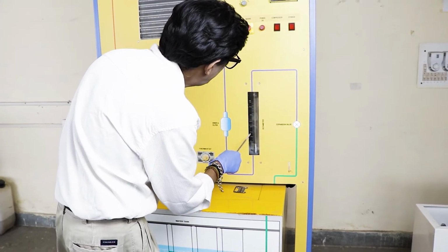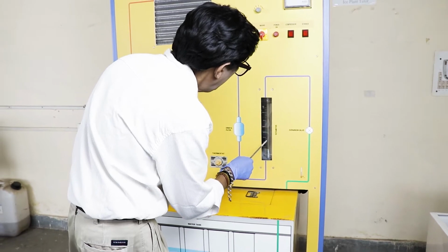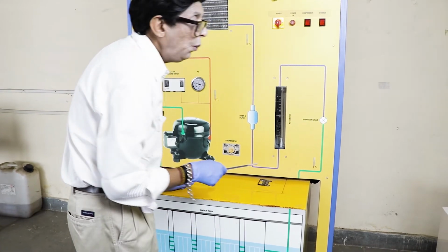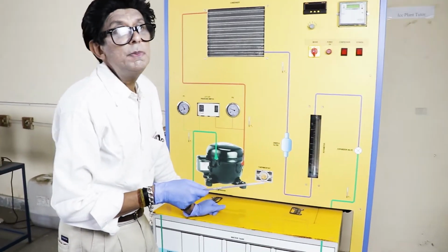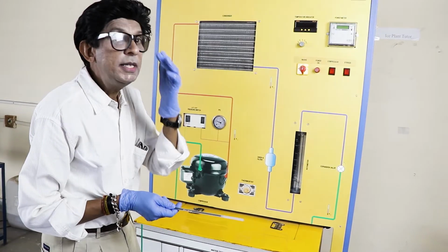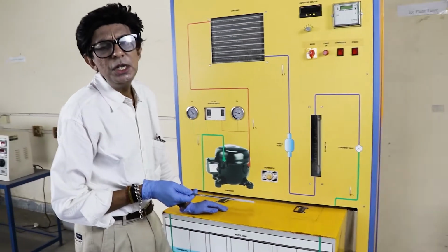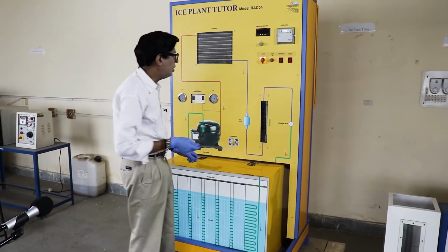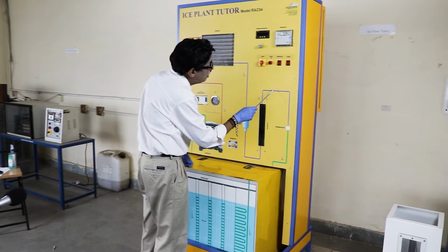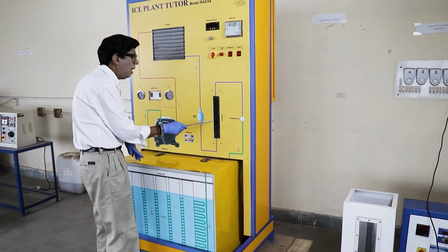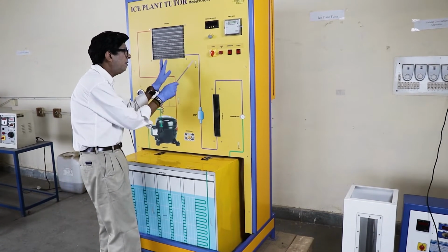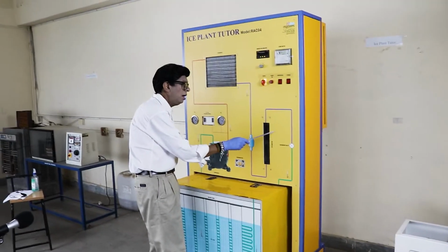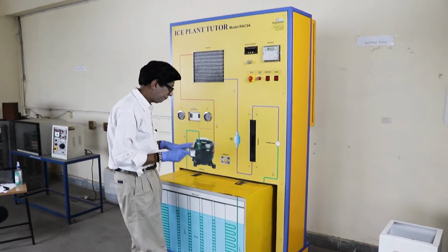So in liters per hour, we are able to find out the flow rate of the refrigerant through the whole system. Now we can convert, because we are not using liters per hour, we are using kilogram force per second. So we have got the conversion system. We convert that into kilogram force per second. We'll do that in the calculation part here. Now the rotameter is not an essential part, boys. This is used in order to make it a working experimental setup. So this is not a compulsory part of the whole thing.